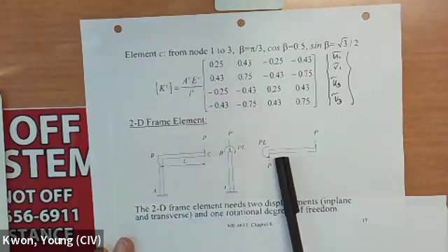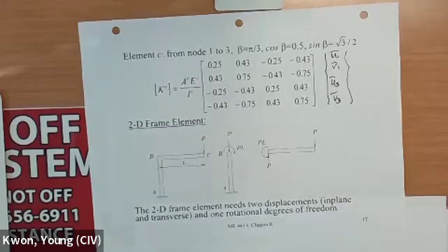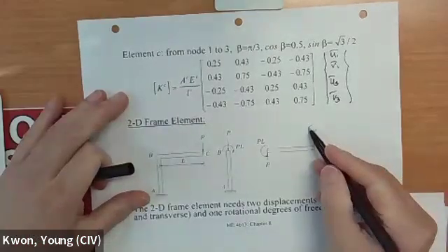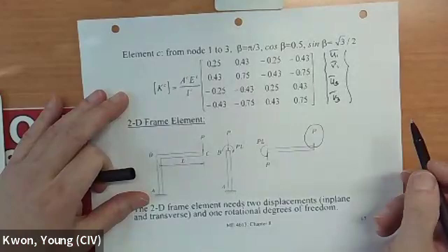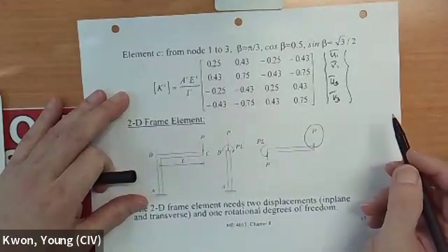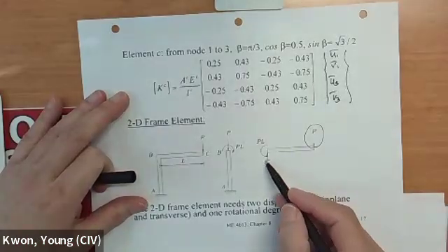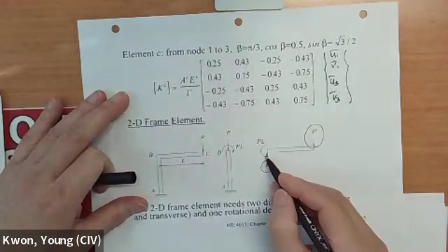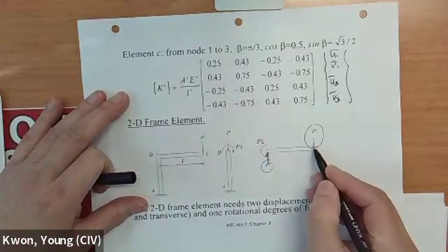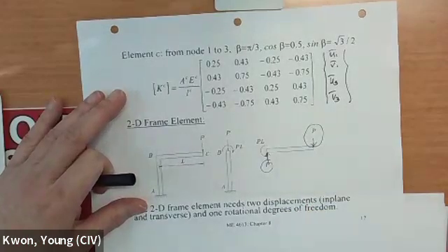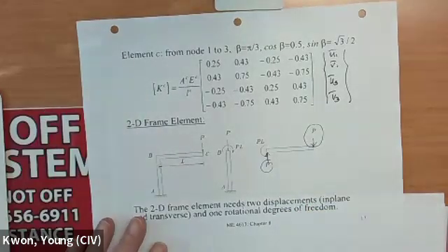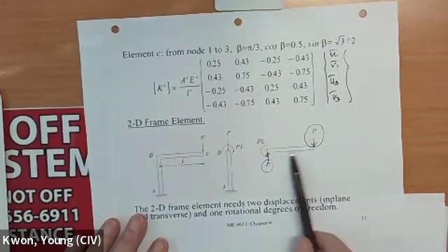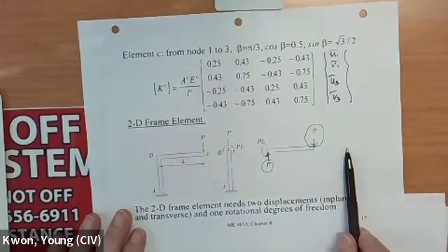From statics, looking at member BC first, this is the applied force, and this is the applied force. To maintain equilibrium, the summation of force and summation of moment must be zero, so the forces have to be the same magnitude in opposite directions. Summation of force in the vertical direction is zero, and there's no force in the x direction, so we don't have to worry about it.